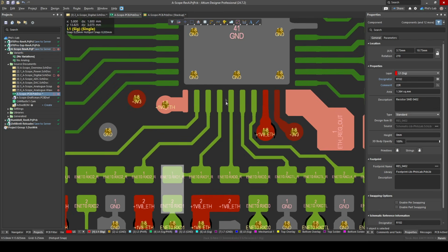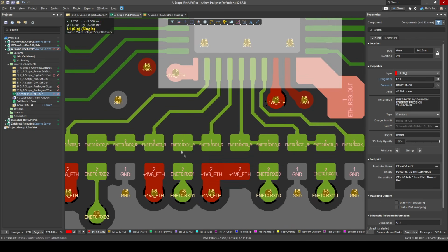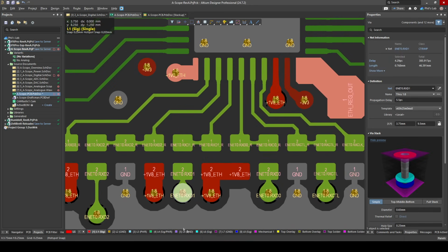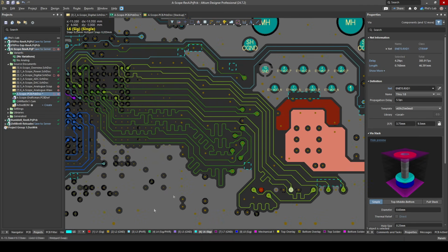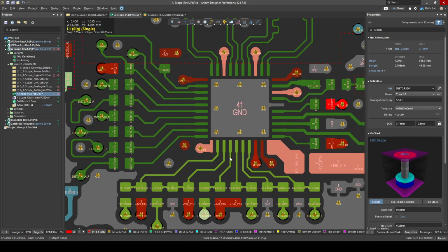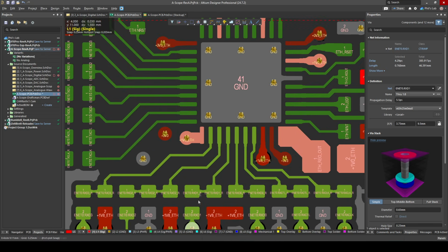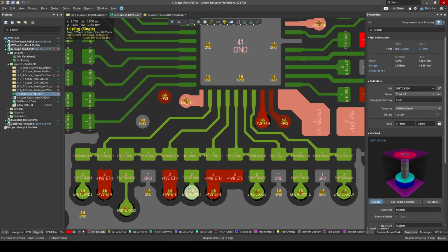They're placed very close to the source because this is source termination, through the strapping resistors, not leaving much stub, straight into the termination resistor, into the via, and then we dig down into layer 6 again, and we do the connections between the MAC and PHY. So again, controlled impedance based on the calculations provided by your manufacturer, source termination resistors close, but we route through the strapping resistor first into the source termination resistor and then into a stripline configuration if you're using a stripline configuration.